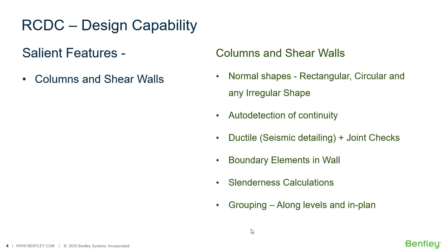So in a way, if your building has four corner columns which have similar loads, and say your building is multi-story, so you don't want to change the design across the height, then you can group those four columns and also group the 4 or 5 levels that you want to produce a single design for all those columns.